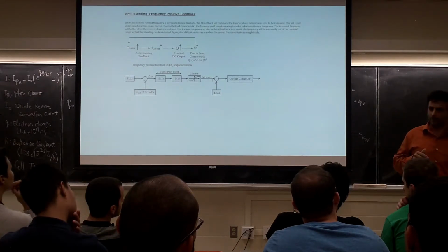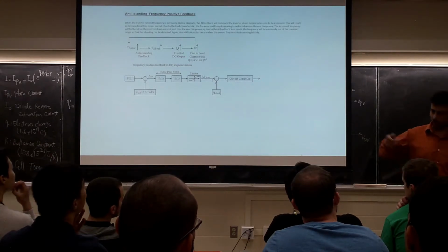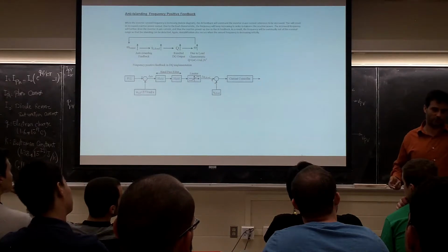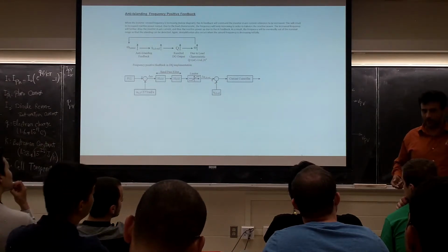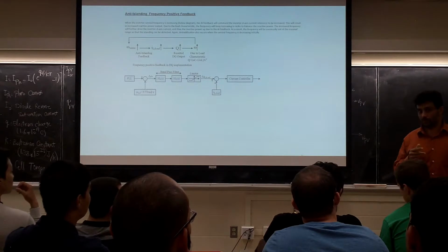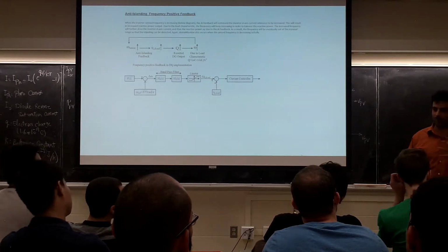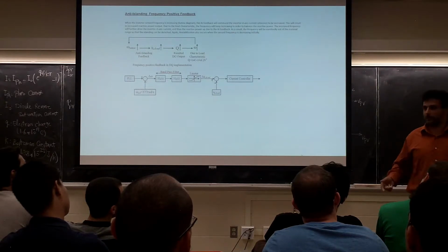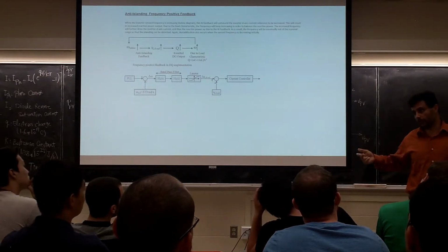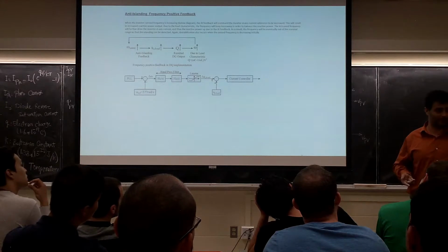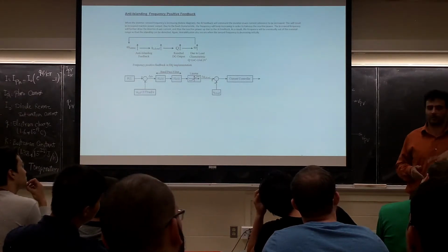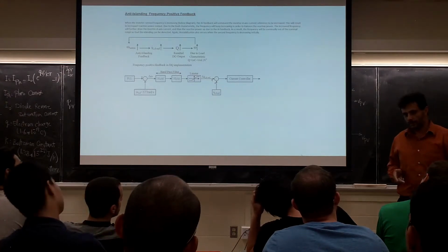There is nothing else. But now companies are working on it because we want to support the load for a home. Even if the grid is not there, I have power generation, so why should I shut down? I can generate some power. Now they're thinking of putting batteries there, because you need a battery to match the load. If you only rely on the solar, maybe you have too much load and cannot support it, or you have less load and cannot consume it. You have to have a battery there, so if you have a surplus or deficit, you can use the battery to compensate for that.